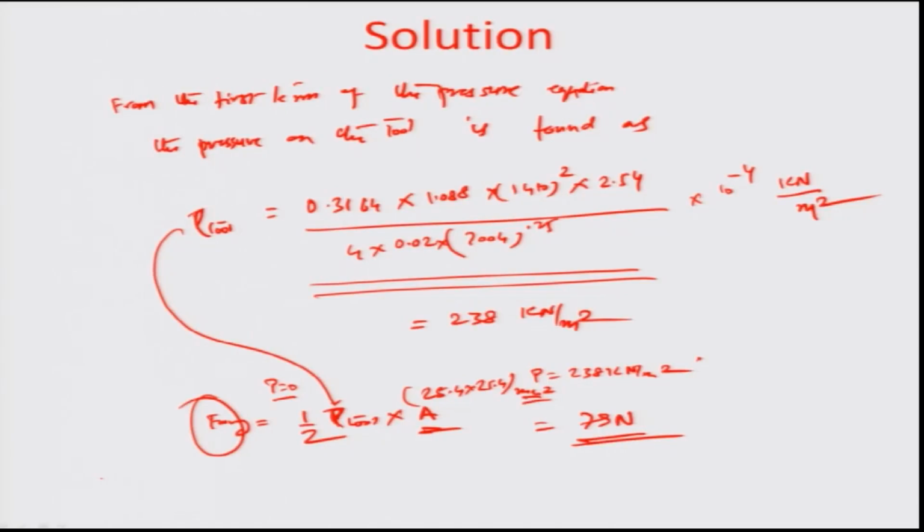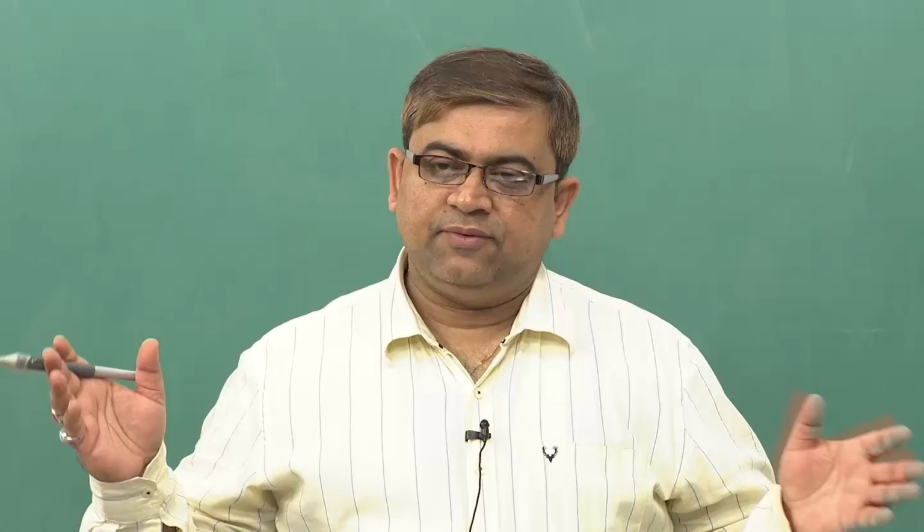In fact, we can also calculate the average force per unit area, and we can ensure that it does not exceed the yield strength of the material, in order to prevent any warping or damage due to the velocity. So, that is how you can design the velocity of the electrolyte flow in an ECM system.